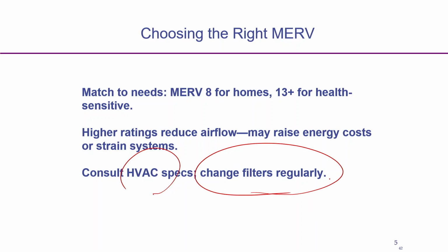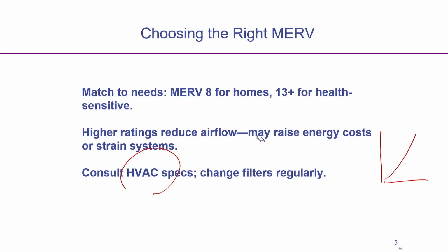If we do not change or clean the filter regularly, it will gradually increase the pressure drop, which will increase the energy cost. That also we will discuss subsequently, how the pressure drop changes with time.